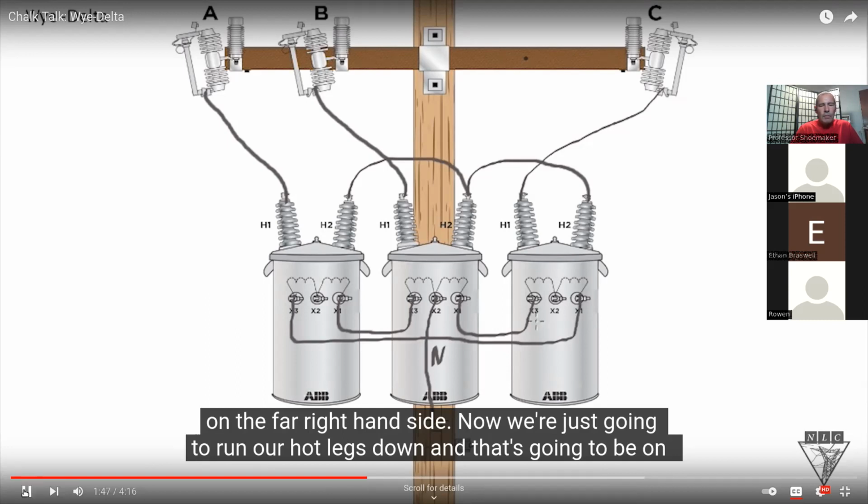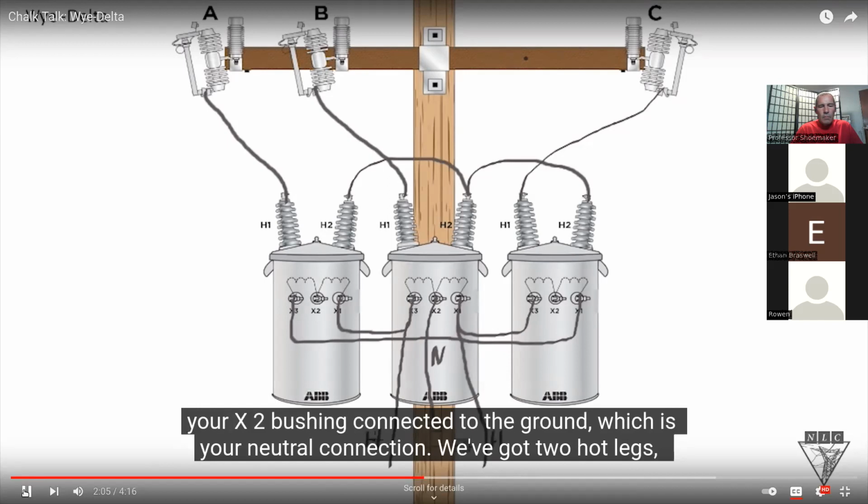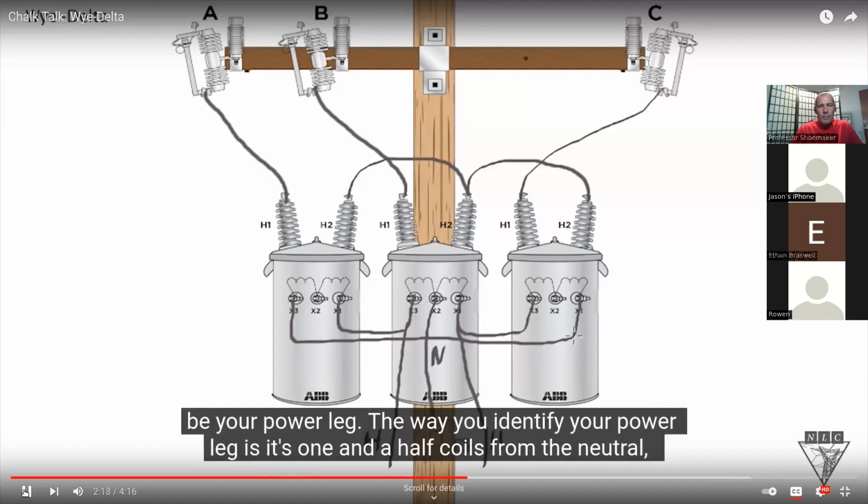Okay, so now we're just going to run our hot legs down, and that's going to be on the center transformer. Your hot legs are going to be the two connections off the transformer that has your X2 bushing connected to ground, which is your neutral connection. So we've got two hot legs. They're off the transformer that's connected to the neutral.